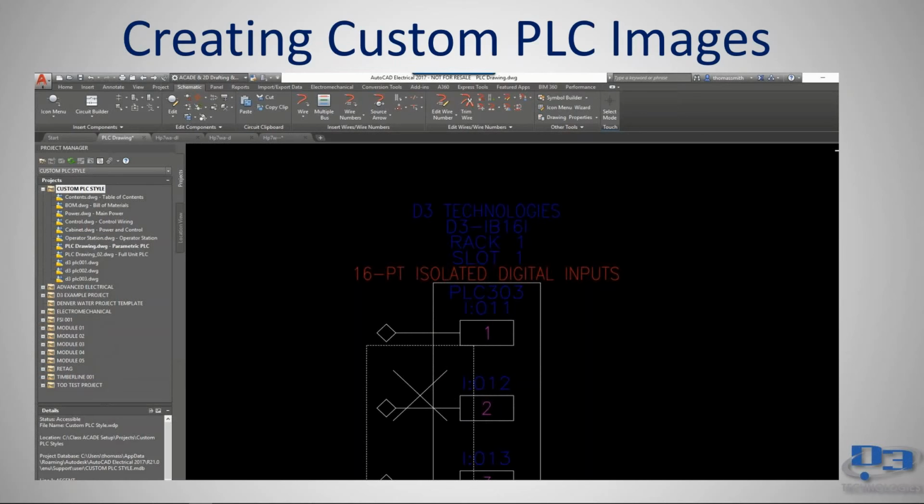So that is the steps of creating custom PLC styles. We must first define the blocks for each terminal type that we would like to utilize in the style. We do that by naming them and saving them in our library location. We take something that's existing, such as a style for, we'll say, PLC style 5. We open the block associated with the terminal type, make our adjustments, perform a save as, remove the number that references the old style, replace it with your new style number, and then save it in the library location. And you will have a fully functional custom PLC style.